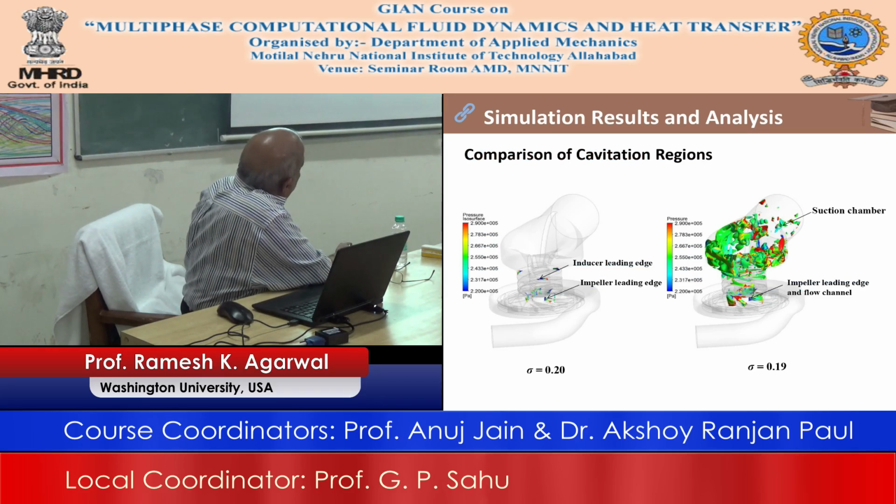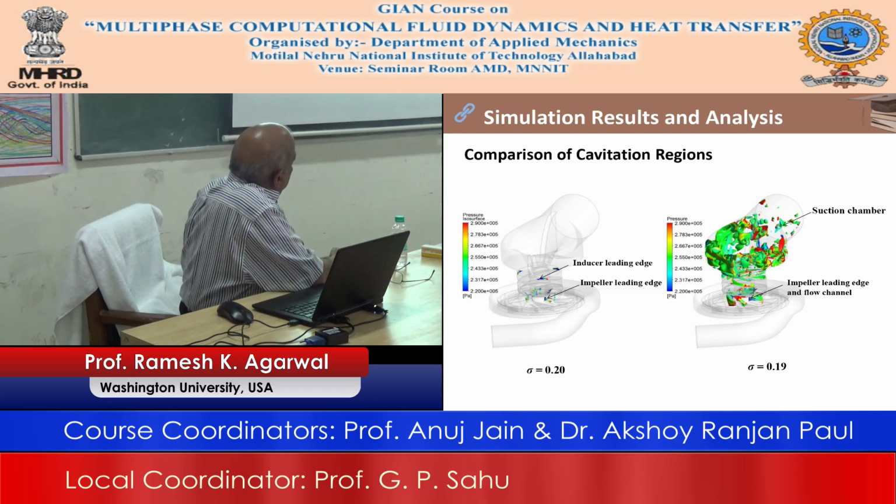This is full of cavitation. This is the impeller, this is the inducer, this is the suction chamber, and you can do a lot of these plots to show that this is the case. These are the flow on the blades, and you see these whole blades are full of air, again using the volume of fluid method, nothing more than that. The procedure is identical to what I showed you.